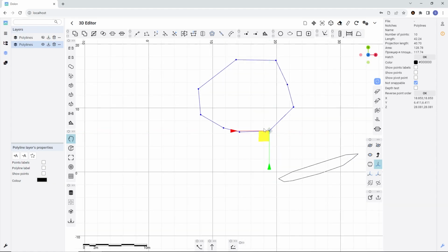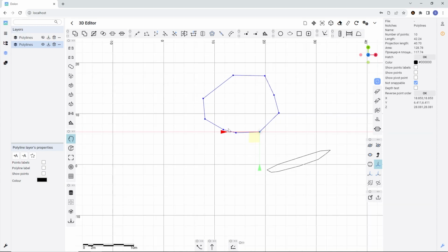While moving objects, you can specify a specific distance to move. Press and hold the Shift key. Start moving. And then release Shift. Now you can input a specific value. Let's say 6. We moved along the x-axis by 6 meters.